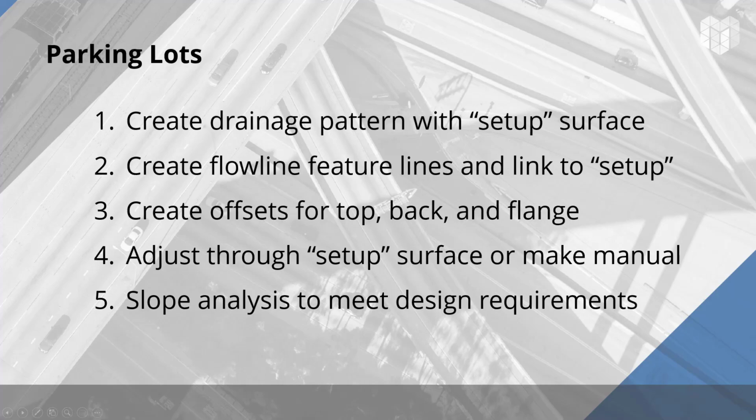When it comes to parking lot grading, we're going to use a concept called a setup surface to establish a drainage pattern for our parking lot. This is a very powerful tool set that allows you to assign a lot of elevations, at least a preliminary set of them, to all the different vertices across your parking lot.